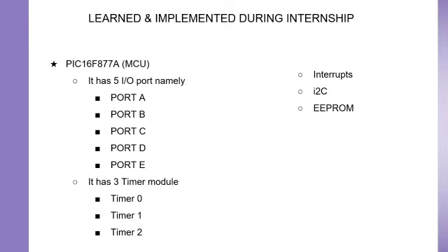So a timer or counter is designed to count the time interval between events. It counts the cycles of the peripheral clock or an externally supplied clock. In the PIC16F877A, timer 0 is an 8-bit timer or counter, timer 1 is a 16-bit timer or counter, and timer 2 is an 8-bit timer.